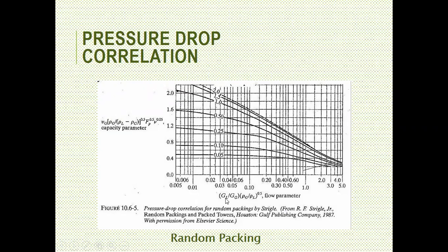Of course, your liquid will be your solvent in the case of gas absorption, and your feed is your gas. Okay? The densities are given in the problem. If not given, you ought to get it in the appropriate property table based on the working temperature or the temperature that is given in the problem. If the temperature is not given in the problem, the working temperature of the equipment, then you can assume room temperature.